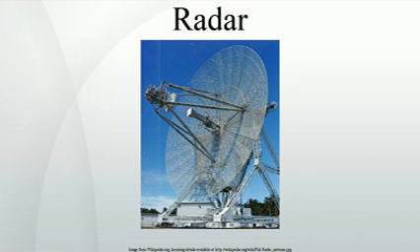Speed measurement. Speed is the change in distance to an object with respect to time. Thus the existing system for measuring distance, combined with a memory capacity to see where the target last was, is enough to measure speed. At one time the memory consisted of a user making grease pencil marks on the radar screen and then calculating the speed using a slide rule. Modern radar systems perform the equivalent operation faster and more accurately using computers.